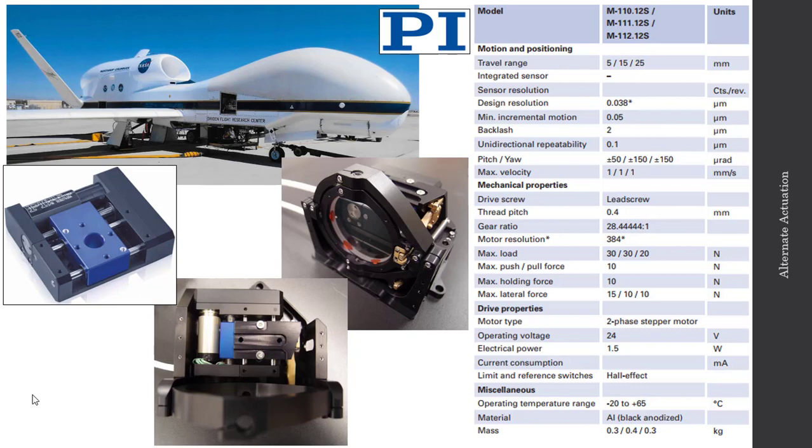So because this alignment process is happening periodically through flight, we're particularly interested in the detent torque of this stepper motor and ultimately this ability of the linear stage to hold and maintain a particular position and keep the mirror in alignment throughout flight. Also of particular importance for this assembly is the precision in steps for the stepper motor, and thus the precision in linear translation of the stage.